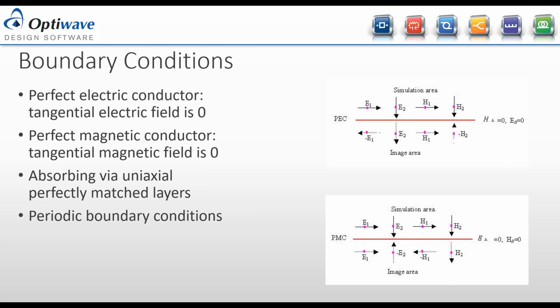So it's sort of a trick to encase your simulation domain with these materials, so that any wave that touches it or reaches or travels through it will start to be absorbed. They have to travel through it twice, right? They have to go one way to reach the end of the simulation domain, and then back to come back if it's going to interact with your simulation domain, and it'll be absorbed in both directions. So you can get a very high absorption of any wave, and so very low reflections from that boundary.